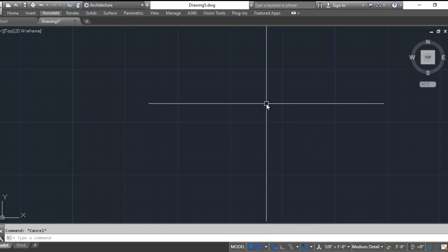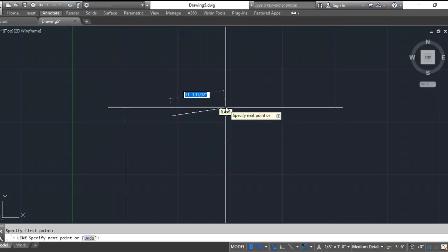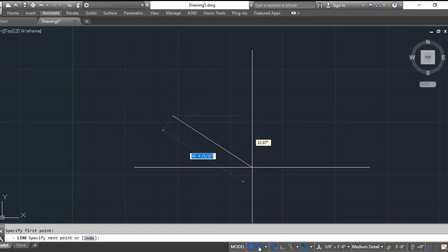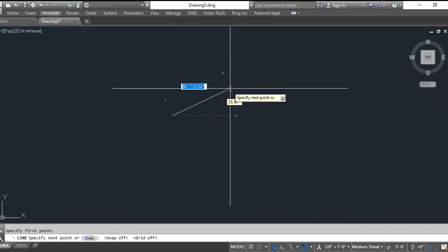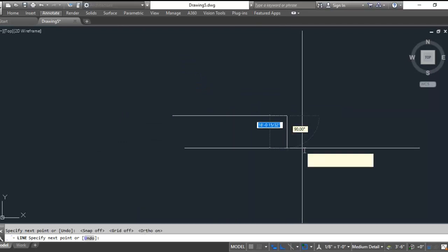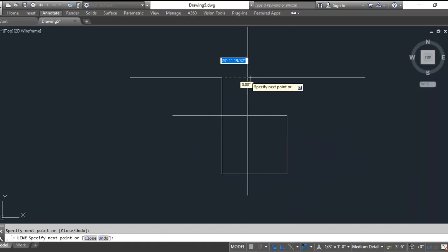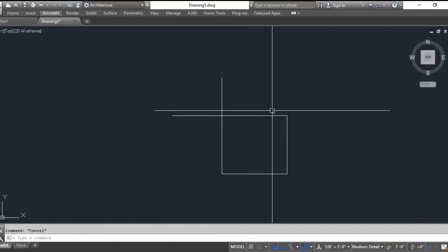The other thing is O-snap and ortho. When I'm drawing a line, right now it's just kind of free around. I have nothing locking it in. So if I hit the F8 key, that's called orthographic, and that locks me into right angles. We'll use that a ton in this class. So make sure that you are familiar with your F8 key to turn on your